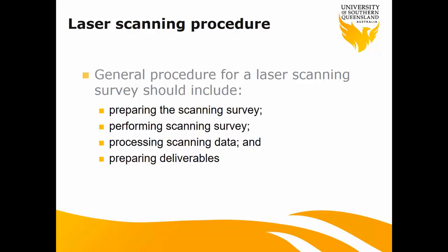After you determine the objective, you can select the suitable laser scanner: a longer range time-of-flight, or a short range phase-based laser scanner, depending on your scanning task. Then process the scanning data, and prepare the final product or deliverables. Depending on the objectives of your scanning task, what's the final product? It's just a cleaned point cloud, or a 3D model, or another product.